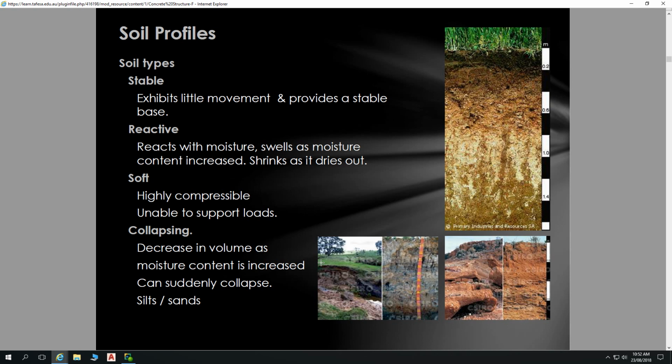That can be the result of the slab design, where if the slab is strong enough to carry all those elements and just do this very easily, well then you've got your whole house doing that, and it'll crack pipes, it'll do whatever. But you've also got scenarios where some soil is pushing right up in one place, but right next to it you don't have that same force, so you've got differential forces within a very concentrated point, getting closer to a shear force. There you can have small amounts of movement, but that transfers straight into cracking of the building.